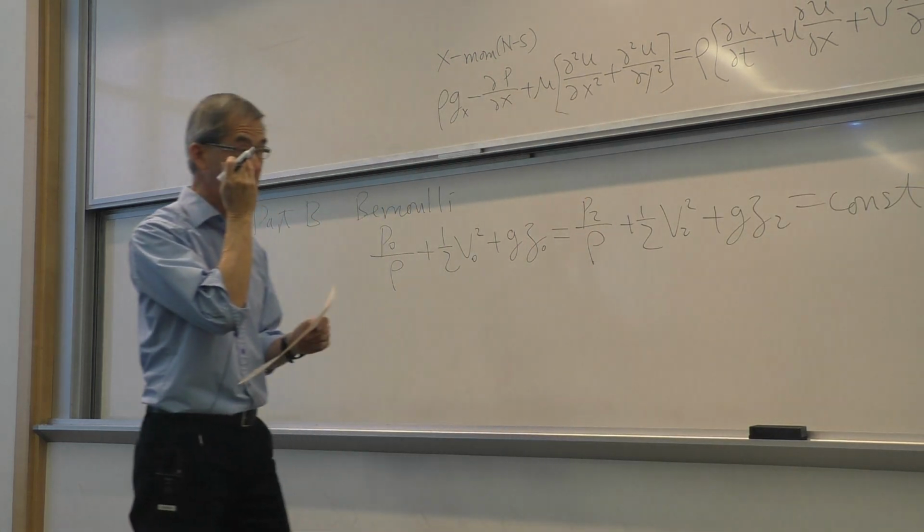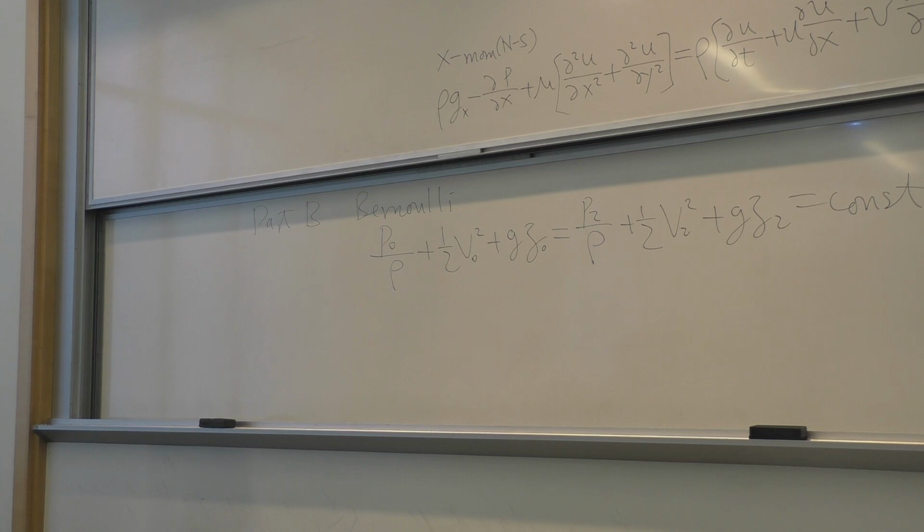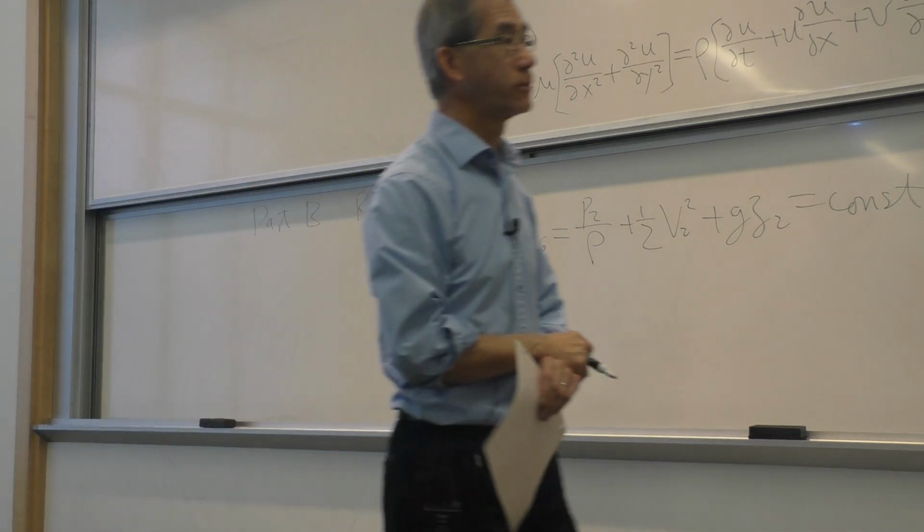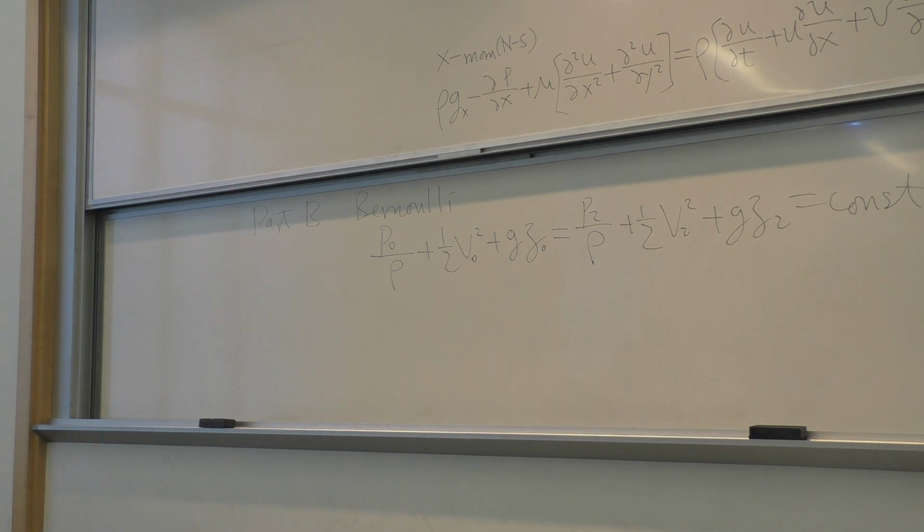And here you can help me to simplify the equation, and I also want to make a very subtle point about the velocity. It's an open water jet. And this is something you need to always remember. What does that mean to you in terms of the pressure within the jet? It's atmospheric. Pressure is PA everywhere within the jet, no matter at what location you are along the jet. That's what we meant by open water jet.